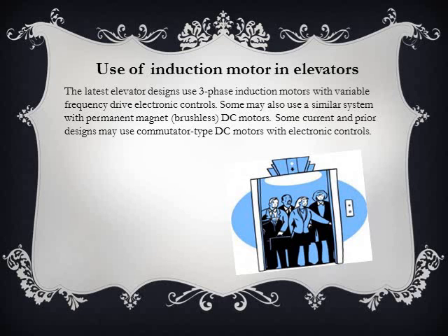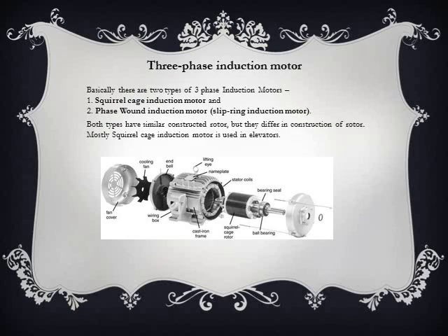Use of induction motor in elevators. The latest elevator designs use three-phase induction motors with variable frequency drive electronic controls. Some may also use a similar system with permanent magnet brushless DC motors. Some current and prior designs may also use commutator type DC motors with electronic controls.